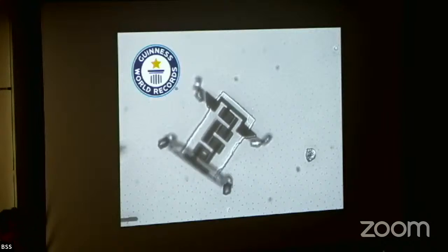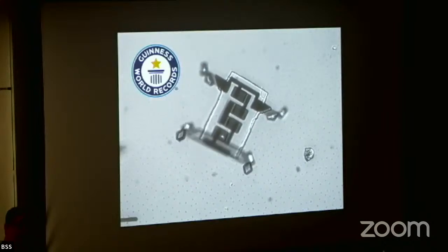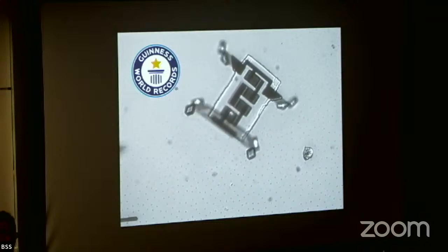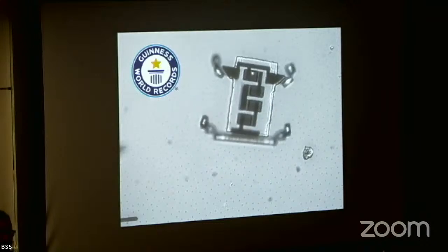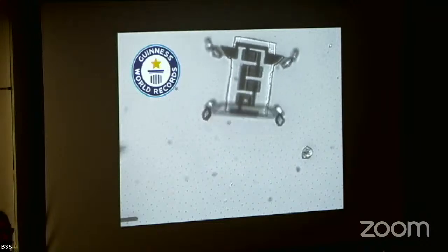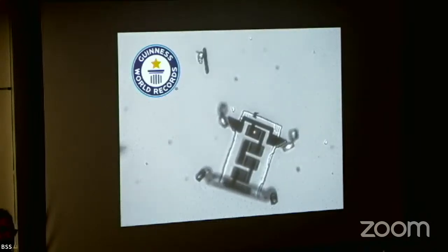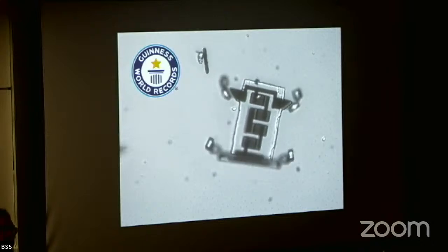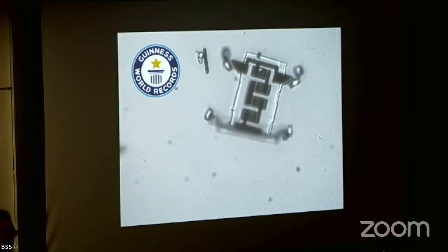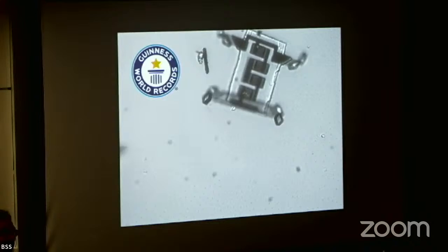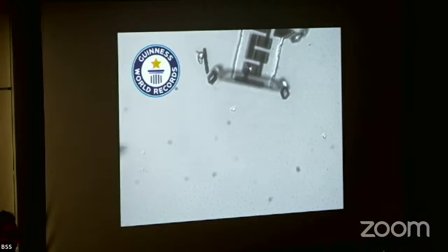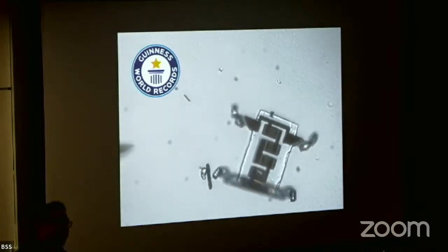Yeah, it's complicated. It took us years to get these recipes, and I'm giving to you all of it in 5 minutes. So there's a lot of details and a lot of really hard work by excellent scientists at CNF, figuring out which materials work. We tried many materials before we got to platinum and titanium for the passive layer.